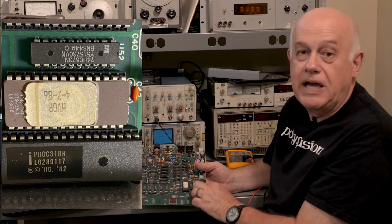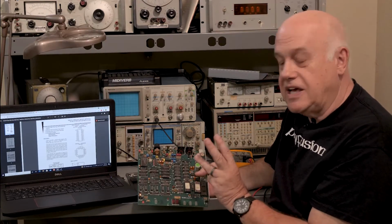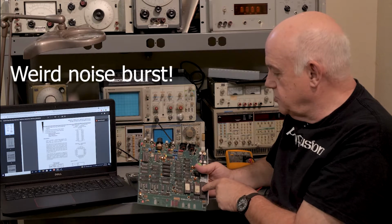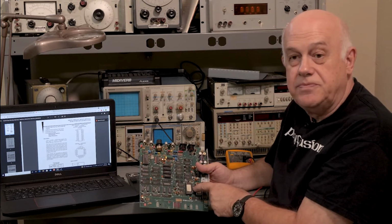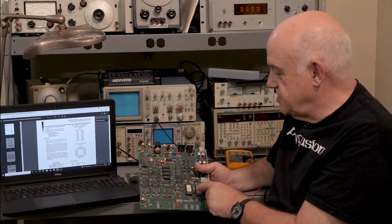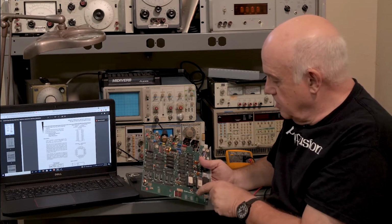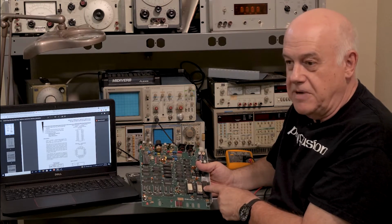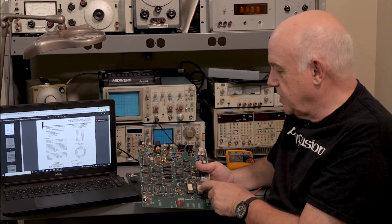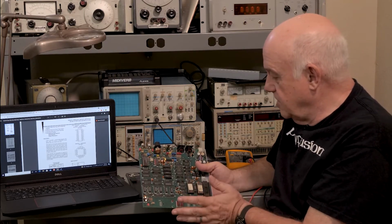You can pull up an 8031 schematic, and you'll see they always tend to have three things on the schematic: a microcontroller, the EEPROM for the code, and a latch. And that latch is what latches the address and data into the EEPROM. So we have those things as well. So I really didn't have to study that schematic. I did a quick check to make sure it's what it was on the internet, and there you go.